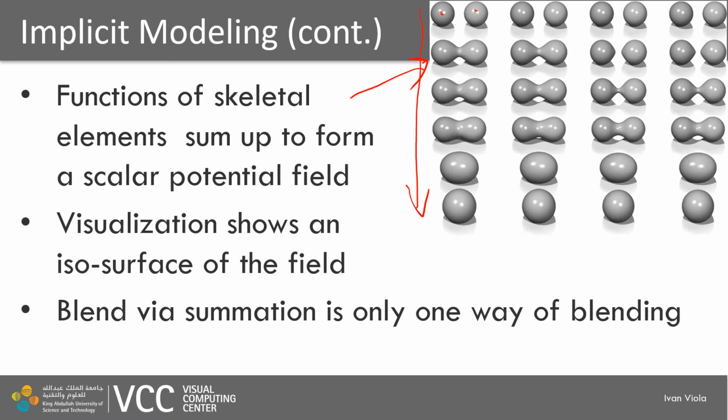So instead of these surfaces being disconnected until they start to intersect, where the intersection would be continuous, C0 continuous, but not smooth, there is a smooth blend. This is caused because we are now summing up the potential fields of both of these two balls. And then the sum will be traced along a certain value of the implicit function.